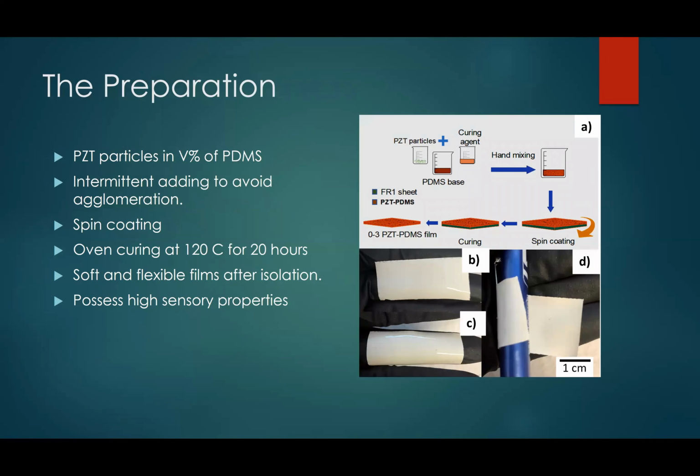To make our sensor, first we wanted to have a flexible piezoelectric substrate. For flexible piezoelectric substrates, PVDF is quite available. But the reason we didn't go with PVDF is that the piezoelectric charge constant of PVDF is very small compared to traditional rigid piezoelectric substrates like quartz or PZT.